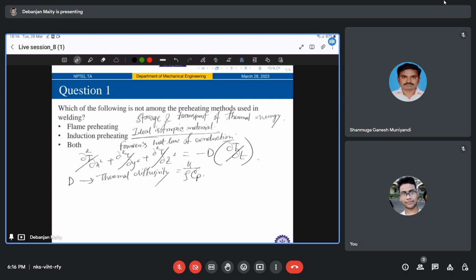And what does it consist of? This thermal diffusivity consists of a combination of physical properties of the metal. You have density, then heat capacity, then the ability to transport the heat, which is conductivity. At temperatures much higher than those of the weld fusion zone, a second mechanism for heat transport occurs. Valence electrons, which are quite mobile in a metal, can provide a mechanism for heat transport, right? So these are some basic concepts of the temperature distribution during welding.